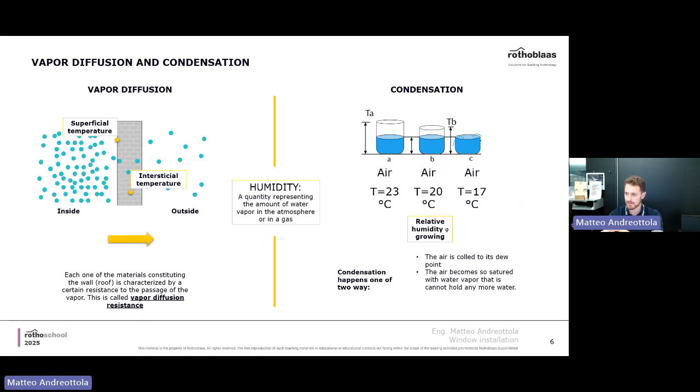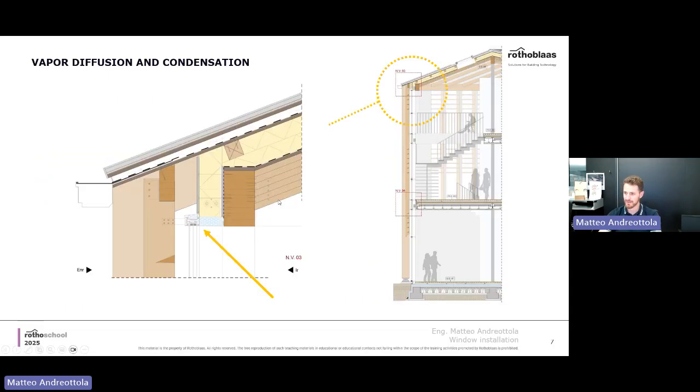Why am I telling you this? Because even with normal characteristics of internal temperature, amount of vapor and outside temperature, even at 13 degrees, you start having condensation risk. This is 13 degrees Celsius, meaning you guys have to do the conversion if you're used to other units. Unfortunately, myself being European, sometimes. But let's go on.